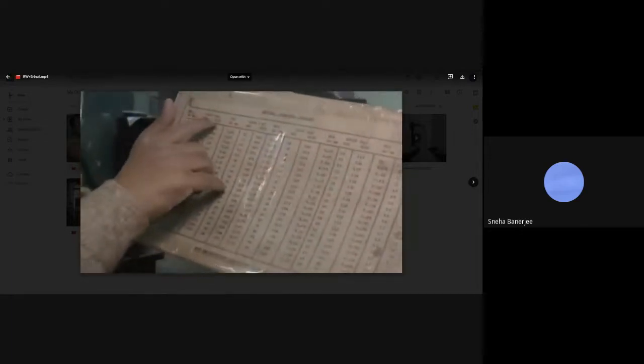In the chart, we have a number of columns. We have the diameter mentioned in millimeter. We have the load. We can use 500 kg of load or 3000 kg of load. In this particular case, we are using 3000 kg of load. So if I can measure the diameter, then according to the diameter, I will find out the Brinell hardness number of that particular sample.